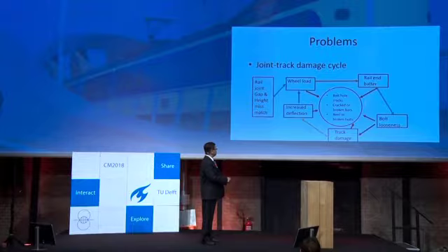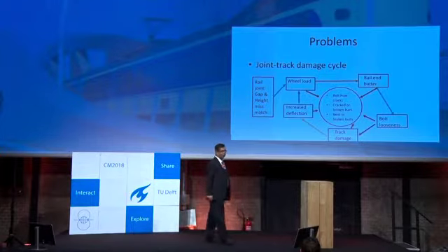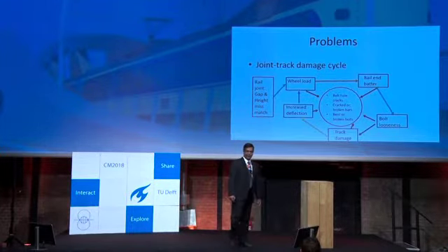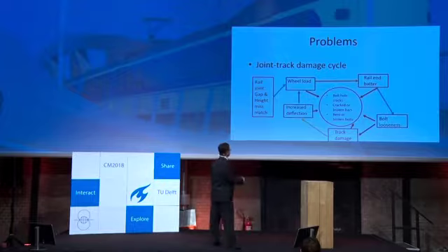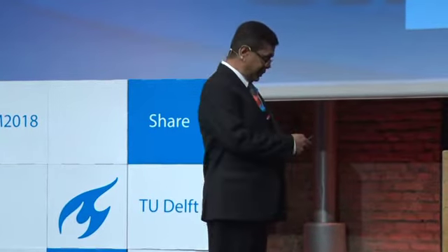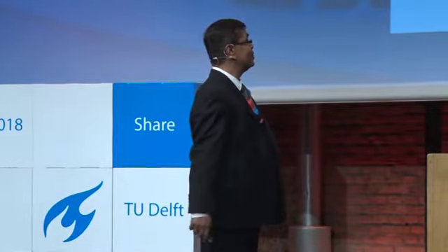Because of this, bolt looseness is happening. As a result, more severe deflection is happening, and hence it accelerates the P1, P2 dynamic force. So this is the cycle that is happening. As a result, bolt hole cracks, broken bars, and bent rail bolts occur. This is an important problem, and we have to notice that.